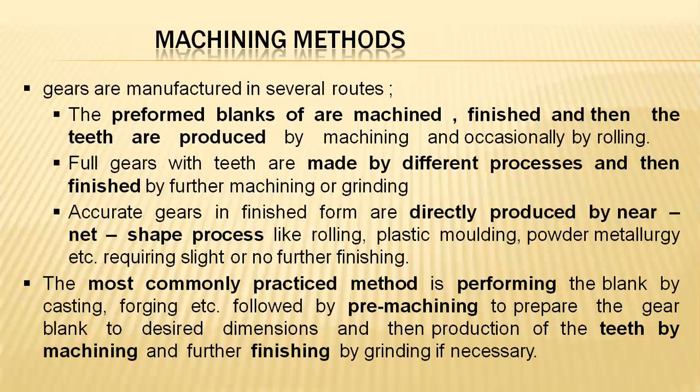Basically, these are produced on a rotational basis, either by fixing the work part within the machine and performing the rotational work by the tool over the work part, or the work part will be rotated and the tool will be in a fixed position, for cutting the teeth on the diametrical axis of the work part.